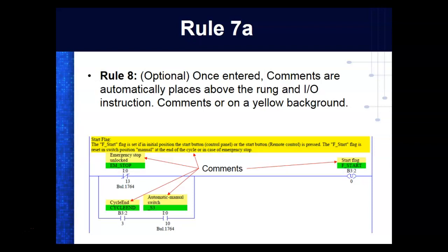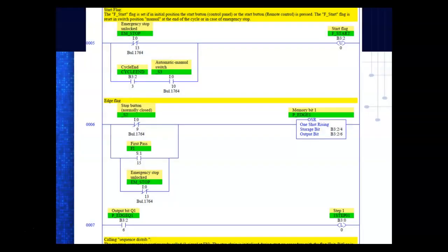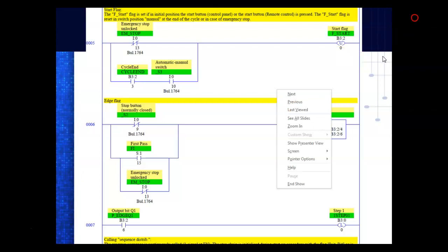If you're a really good programmer, you're going to use comments, but definitely you want to start using symbols because, like I said, most of your newer PLCs don't call them symbols anymore. They call them tags, and these tags are usually required. That's why we're trying to get y'all used to using them here. And notice, what do they use a lot? They use latch and unlatch. Once you learn how that works, they use that a lot.